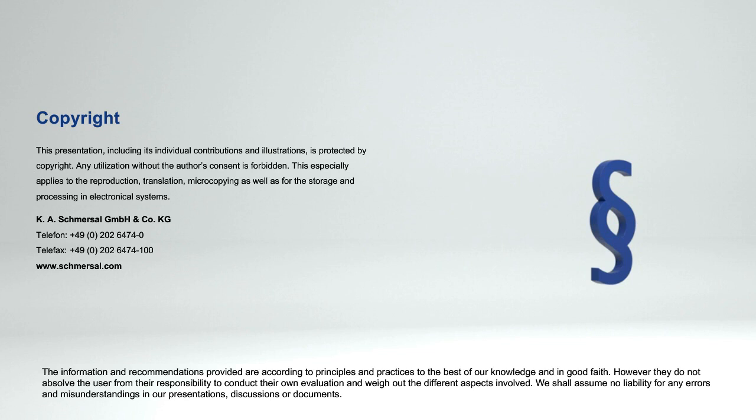Very good. Jameen Patel from Revitech Engineering says, can you please explain fault exclusion? Sure. Fault exclusion is, I guess phenomenon is not the right word, but in certain control categories, you did not necessarily claim a category without thinking about certain fault exclusions. One that you see talked about and debated a lot is a key interlock switch. You've got a mechanical key that goes into a switch where the switch has two independent contacts to go to your safety circuitry. On the surface, it looks like you have redundancy, but you could have a single point of failure with the key breaking and staying with the switch.